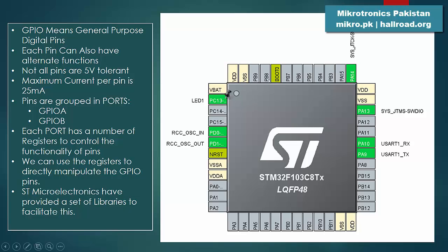So the same picture, a little bit more clear, I hope you can see. This is the picture of STM32F103C8 microcontroller. And you can see the power supply pins VSS and VDD. This is also VSS-A and VDD-A. Both these are also power supply pins, but these are actually for analog circuitry. They have been kept separate from these pins